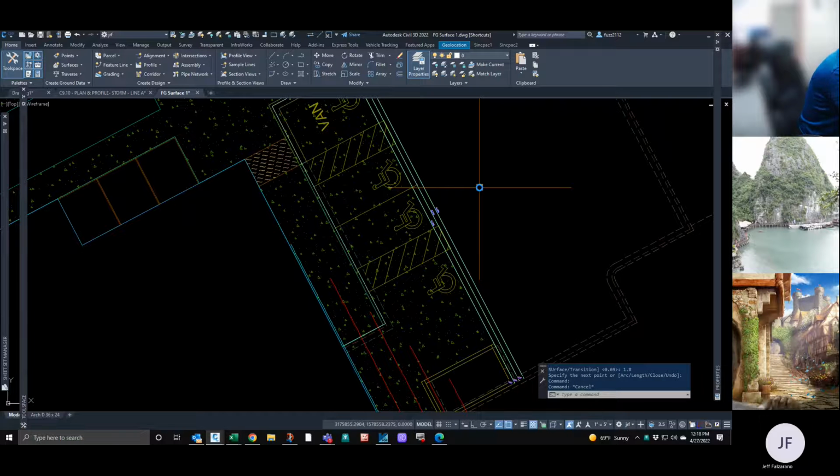They've changed it a couple of times over the past couple of years. It used to be 2%. But nobody would build it to 2%, and they throw a level on it and it's over 2%. So then they went to 1.8, so if you throw a level on it, plus or minus, you get that 2%. And then Denver got even more strict and said, well, nobody is building it to 1.8, so let's just do it to 1.5. But 1.5 is probably the minimum.